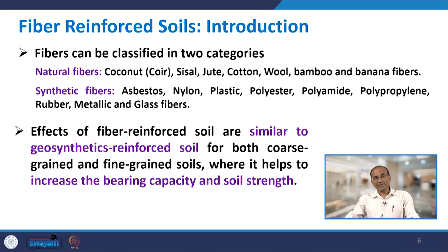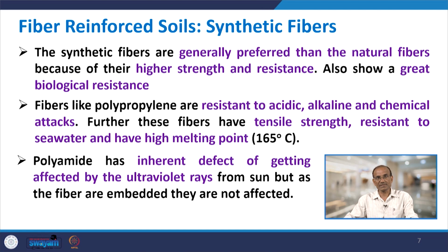Now, the effect of fiber reinforced soils is similar to geosynthetic reinforced soil for both coarse grained and fine grained soils, where it helps to increase the bearing capacity and soil strength. So, addition of fibers inside the soil will help in increasing the bearing capacity as well as its strength. The synthetic fibers are generally preferred over the natural fibers because of their higher strength and resistance, and they also show great biological resistance.